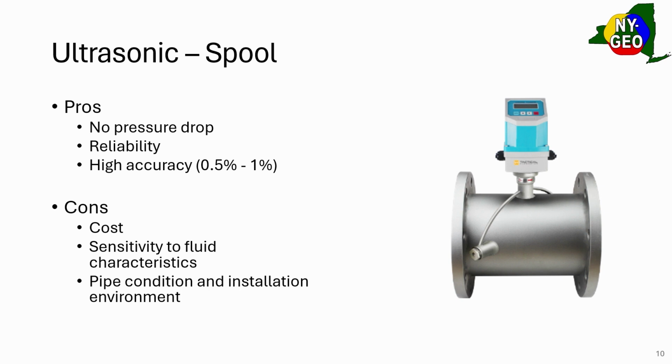Yeah, that's certainly possible. I'm sure it's the same type of meters. We'll talk about software in a bit. There's probably a communication layer that's communicating to that BTU meter that's pulling that to the SCADA system. It's a lot cheaper because BTU meters are pretty costly. So you get to eliminate the physical meter and just have the same data. So there needs to be sensors. Right. Oh, yes, so sensors are there, but not a physical BTU meter.